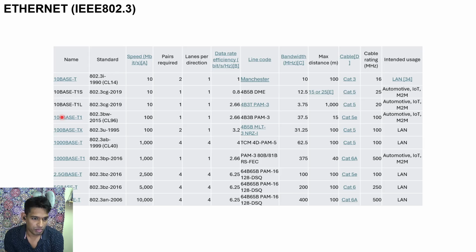There is no sufficient bandwidth for the master client, that is, the RCB, report control blocks, to function. You have to connect it to a managed Ethernet switch with 100 base T. With SPAN, these 100 base T managed switches have spanning tree protocols which can avoid loops in the network. But this D-Link switch does not have any such protocols, because it will not detect loops, and it will not have a spanning tree algorithm.